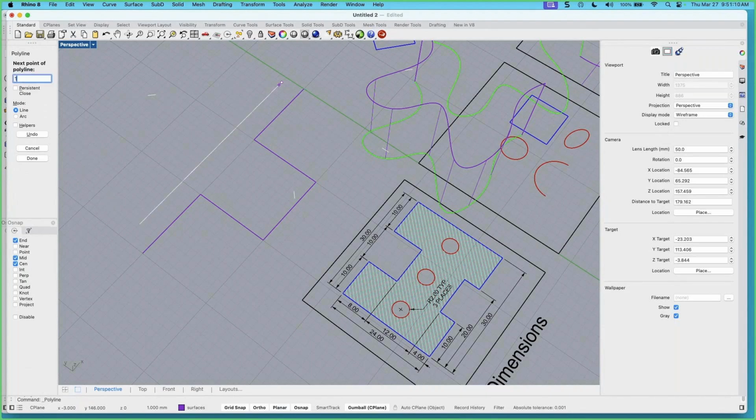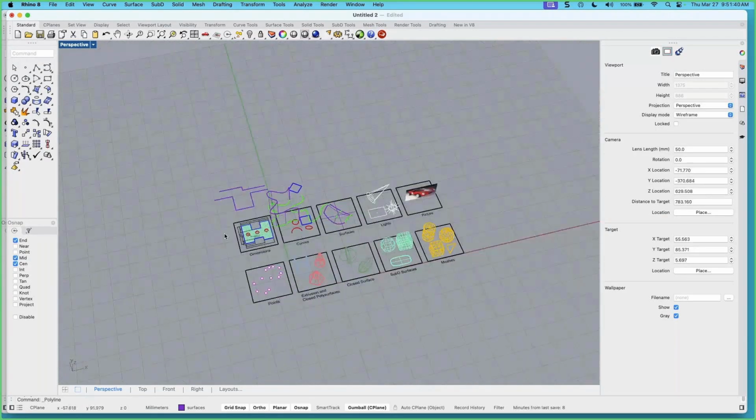Okay, and how about meters? All I need is an m, so that's quite a bit longer. The default is millimeters since that's the unit of the model. I can even put in the foot mark, but I'll type in 1 inch and Rhino takes care of doing the conversion. Otherwise, if I just type in the number, then Rhino will be doing the units of the model. So keep that in mind.